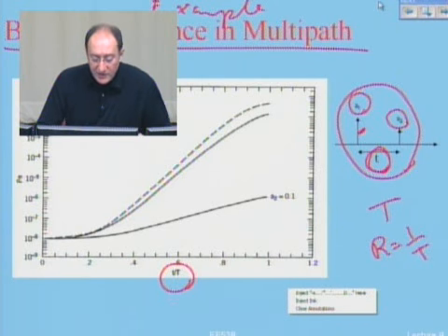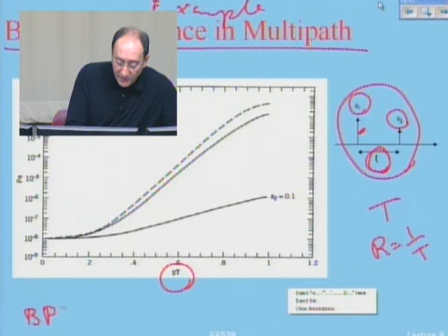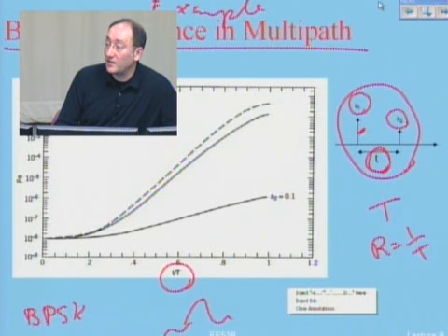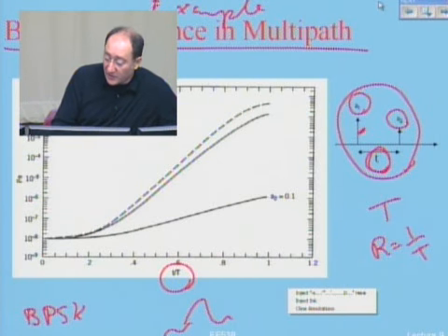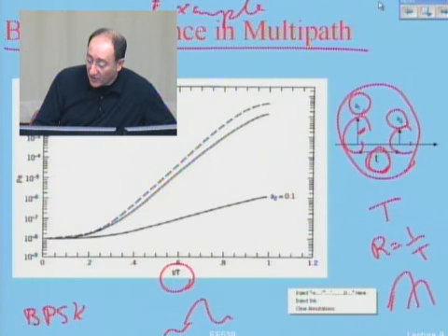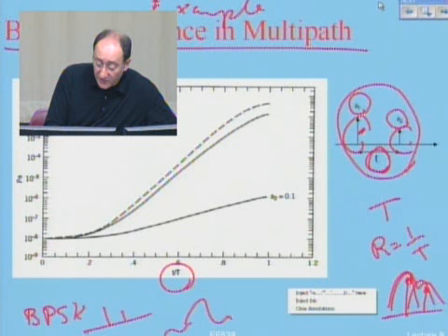And then what I do is I take basic binary PSK modulation, for example, and I generate my pulses and calculate the error rate. How do I calculate the error rate? I take these two paths, send one pulse, receive another pulse, create the overall impulse response, sample it at T, and find this equivalent discrete impulse response.